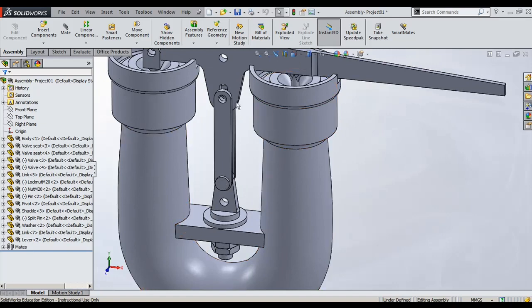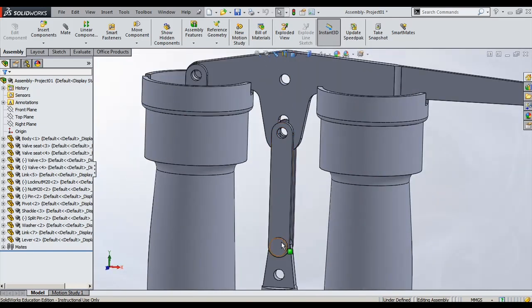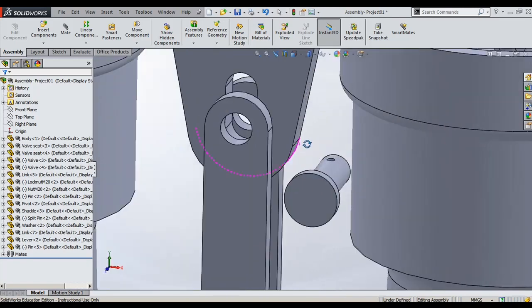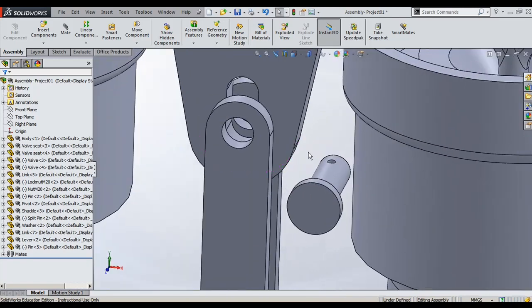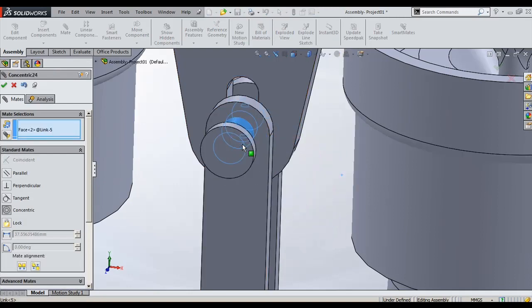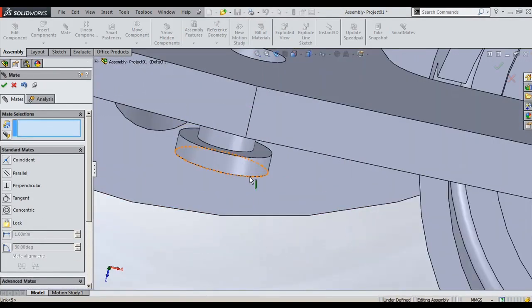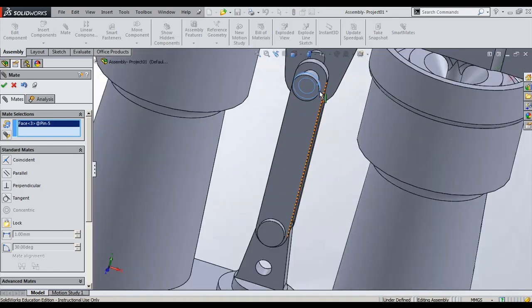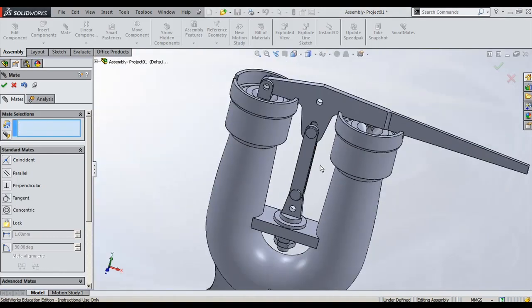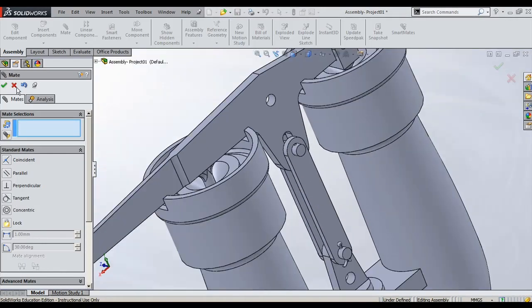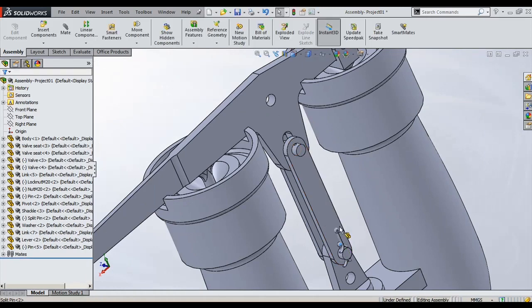but it will once again involve using the mouse going here and there. To avoid this, I can just use the Control key, and if I press and drag, another component will be generated; the component will be copied. Now as usual, I'll choose the mating condition for this, and this should be concentric, and similarly this face should be exactly on this surface, correct? Yes.